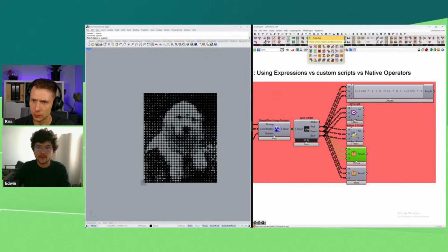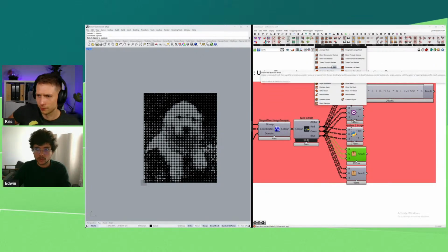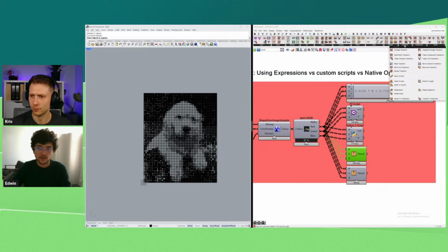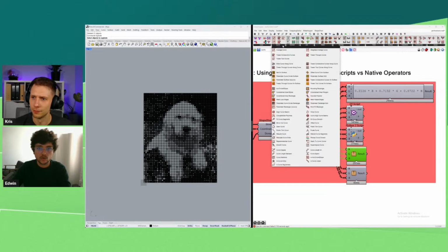Okay. So if I go to Pufferfish, you have many mesh operations here. We were talking about how meshes are very important, but we also have, for example, transform operations and everything in between. I use Pufferfish a lot to, for example, twin between curves, and in that way I can create the wireframe of a soft surface.